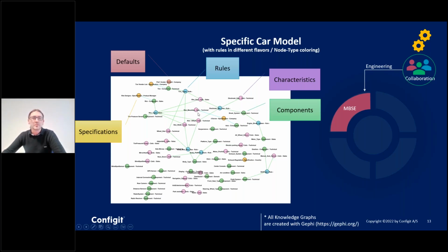We also have some specifications in between here, which brings the connection between the rim mounting and the axis, where we have a company specification that we're using 5 screws, not 4, not 6, we're using 5. And also down here, we have a specification for the exhaust system, so a regulation in the different countries. So that way we can build up the product model.